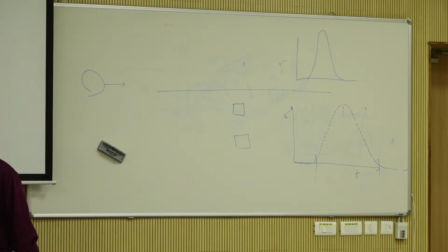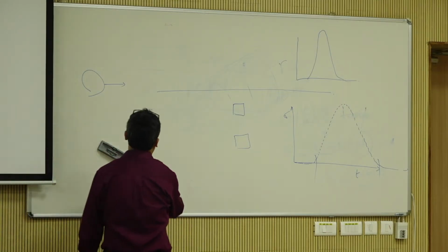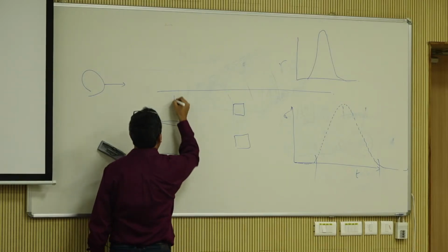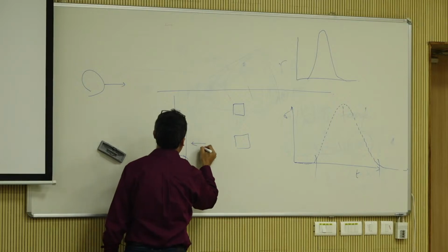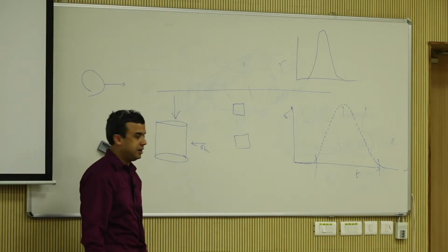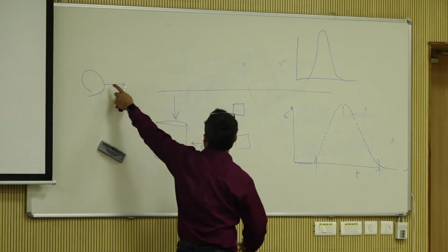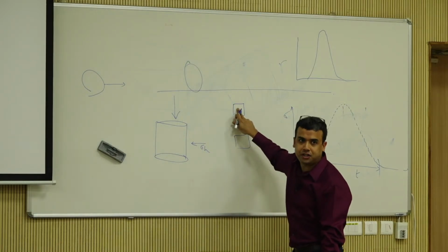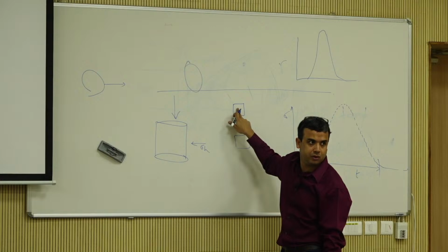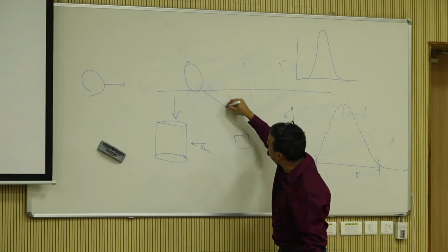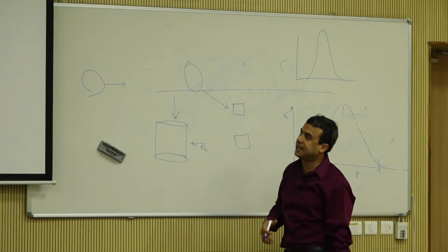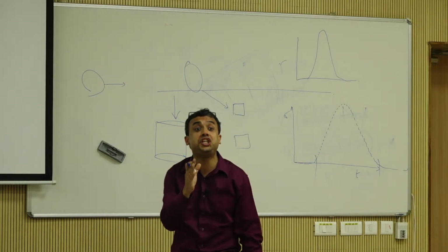But there is actually another thing that's happening here as well. In triaxial testing, we are always aligning the sample like this, and we are loading this way and confining this way. The problem is when the wheel is over here at one point, this thing is not just experiencing vertical load. It has components this way as well, right? So it has horizontal components, it has shear components.